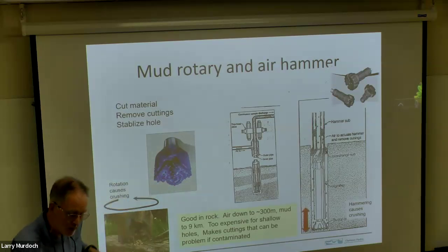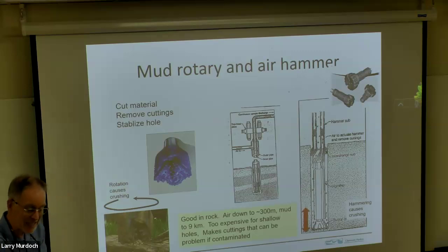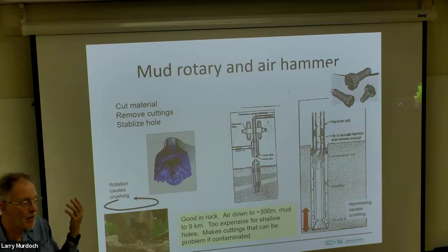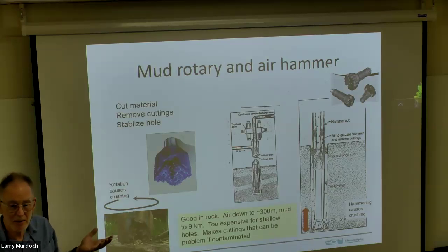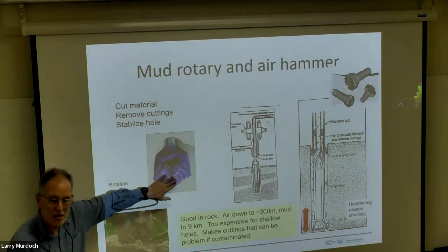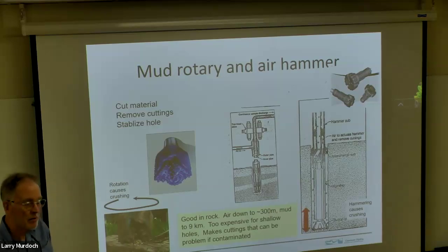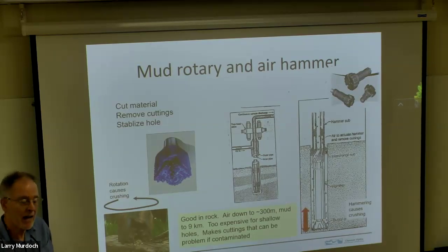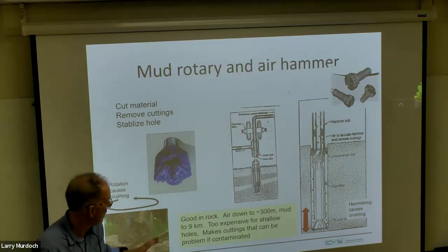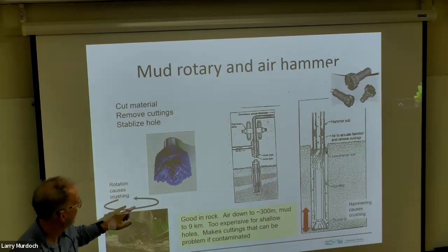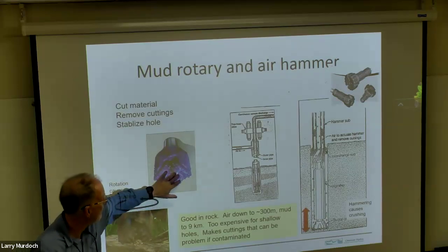Because if you try to cut rock by shearing it, the bit is going to wear out quickly, and you're going to have to pull it out. And if you have to do that often, and you're trying to drill a deep hole, it's going to be really expensive because you're always replacing the bit. This thing lasts a lot longer, so you can drill a lot deeper and a lot further before you have to replace the bit. Okay, so that's one style of bit.